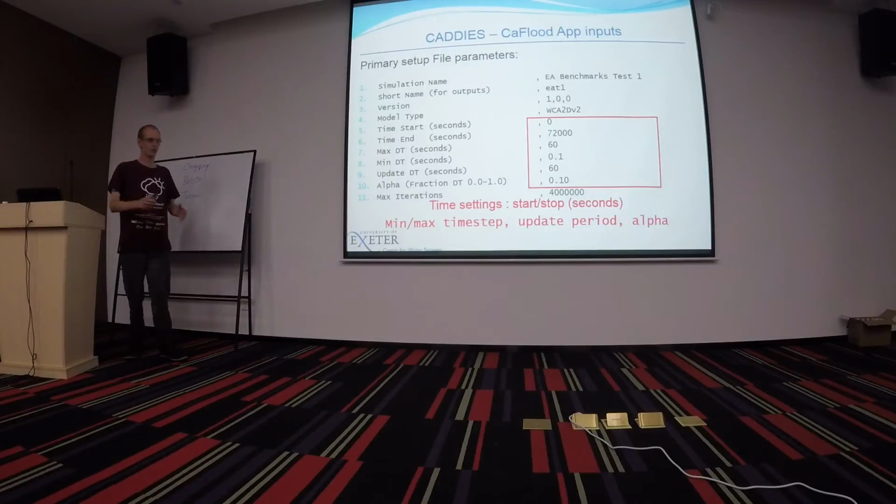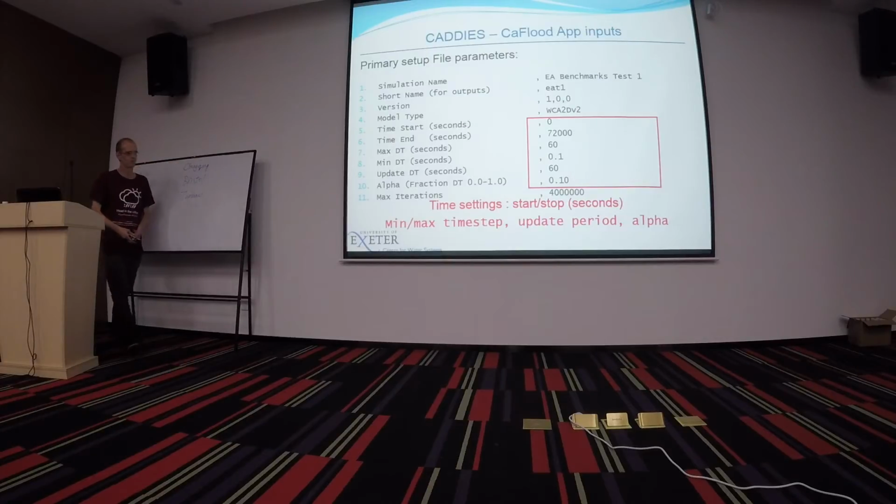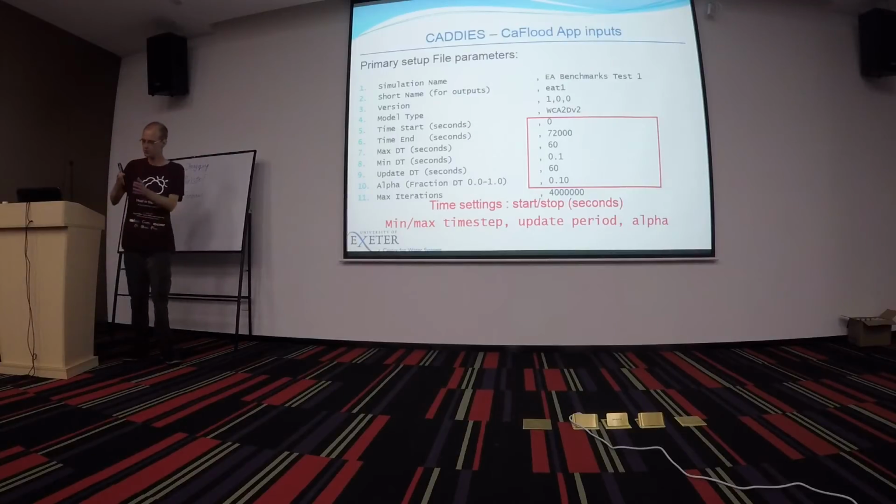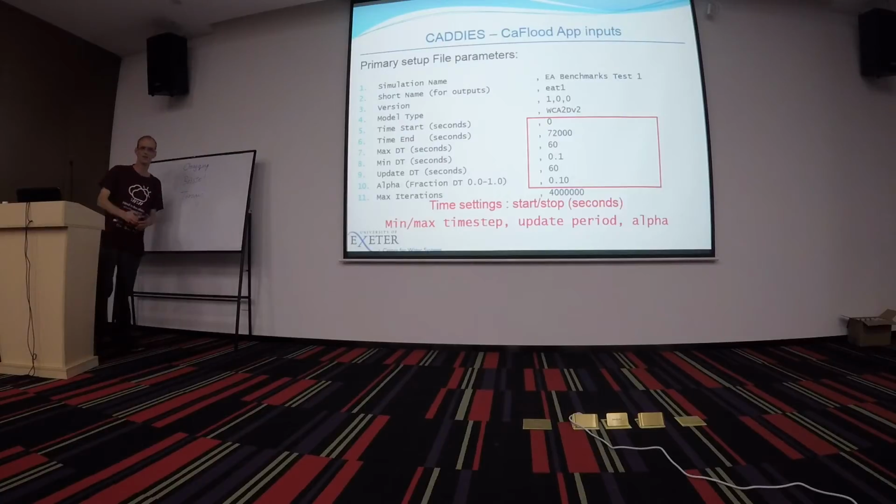Once we've got how long we're going to simulate, we need to know the time step that we're going to use. And since, as I say earlier, we're going to use an adaptive time step, we need to know the minimum and the maximum. Generally, you leave those alone and let the adaptive time step adapt. And rather than adapting it at each and every iteration, because that's quite expensive computationally, we do that at every certain time interval. So every 60 seconds we will check the velocities, and if they are larger, we will reduce the time step. Conversely, if they're smaller, bigger.